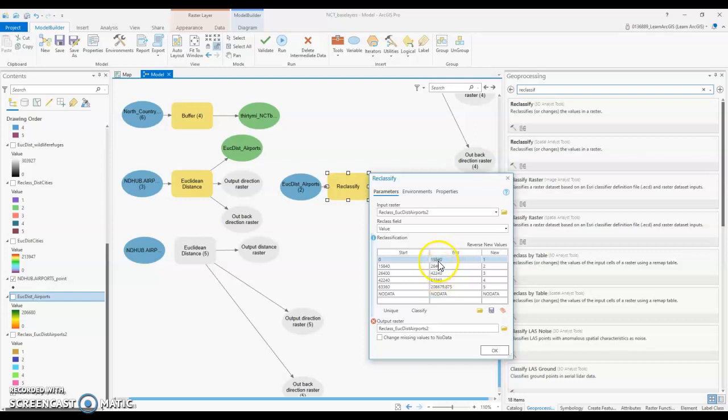So what I'm doing, let's say 0 to 3 miles. I'm going to convert 3 miles to feet. So 15,840 is going to be ranked a 1. I don't want to be within 0 to 3 miles of an airport. That's not suitable for my goals. And so we'll just go on and on until we get to a 5, the farthest away. Make sure you stop and start with the same value so you don't have any gaps, or else they're going to show up as no data.